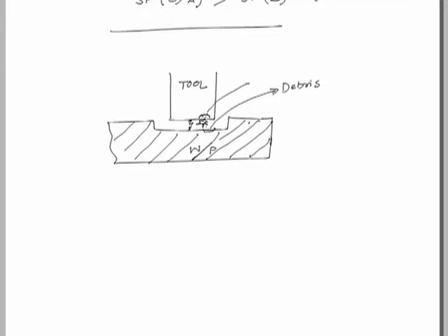So, this will also go as small debris into the flowing dielectric. Therefore, because of this small removal of material from the tool surface, the tool also gets worn out with continuation of this sparking process.